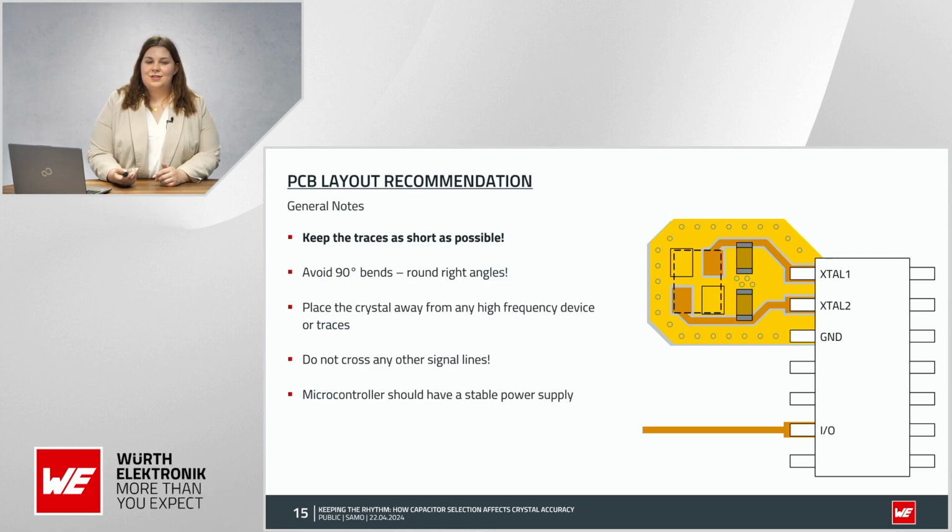You should place your crystal away from any other high-frequency device or trace, because that can interfere with your frequency and maybe cause the crystal to work at a totally different frequency. You shouldn't cross any other signal line, because that can also interfere. And you should have a stable power supply, meaning if the power supply of the microcontroller changes, that can also affect the frequency.